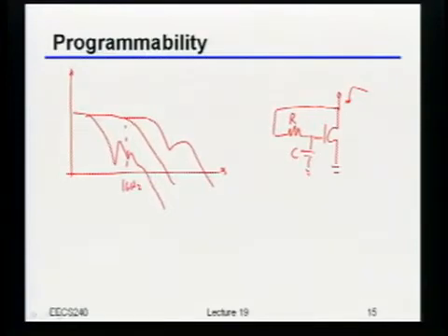So what frequency will this thing start to look like a higher impedance? If I looked at the Z. I think somebody said it. Just repeat it. 1 over RC. Yeah, it's just 1 over RC, right? Because that's the frequency at which the low-pass filter kicks in, and so you get less feedback onto the gate and basically you get less effective GM, right?